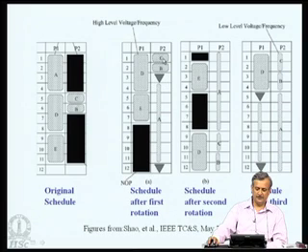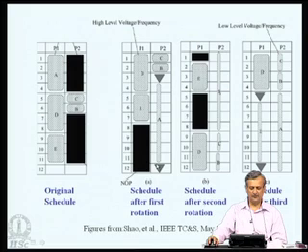So, processor 2 executes C and B, and then it reduces the voltage, that is why there is a linear bar here, executes A in a lean mode, that is, a lower frequency mode, and then again changes the voltage back to its normal. Now, during this time the program is really doing nothing on processor 1. Okay. So, during this time there is some saving, because we have actually reduced the voltage of processor number 2.